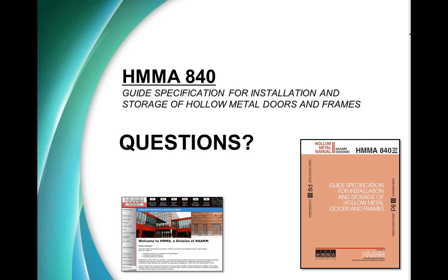The installation of the wall construction and wallboard needs to be correct, and the size of the frame, the throat opening, needs to be correct to match the wall. If all that fits, everything should be installed within like 15 minutes. And that's why they're very useful at the end of the job, where they can be supplied, finished, painted, and ready for installation.